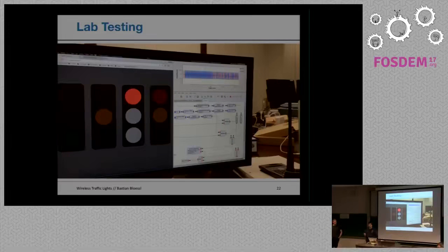So the configuration always seems to be that one is kind of the master of the communication, and the others are just reporting back periodically so that the master actually knows that what it was transmitting was actually received. So not that the master turns green and the other doesn't. And also on this frequency, you don't have to space them that close because you're on 170 megahertz, so you get some range.